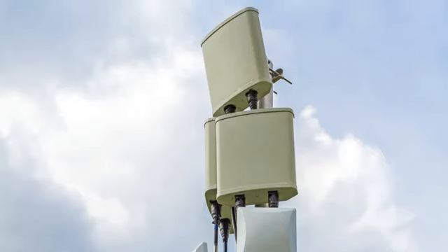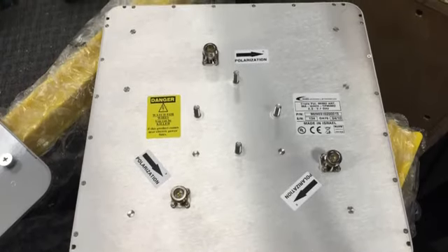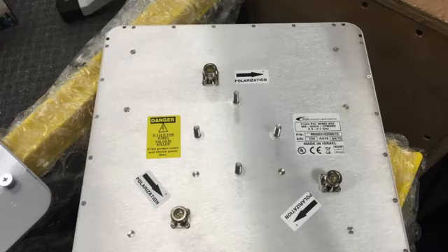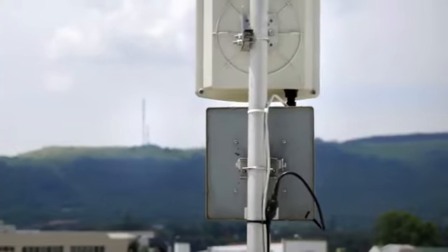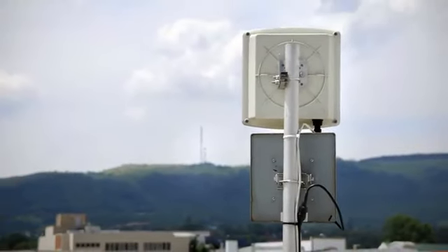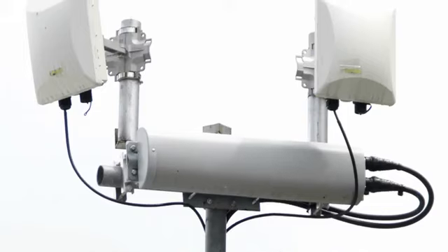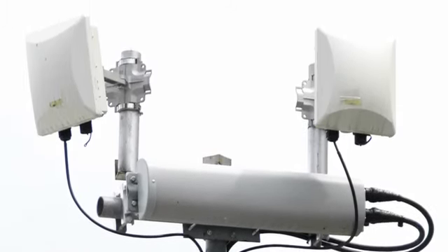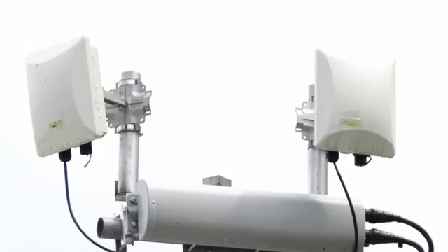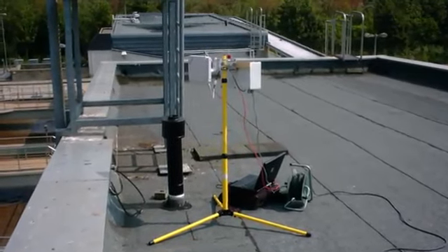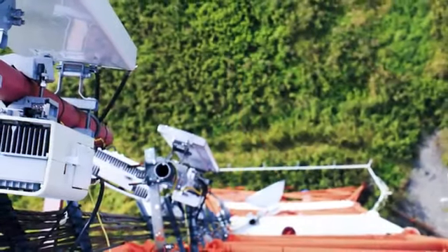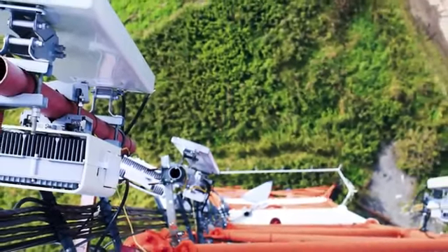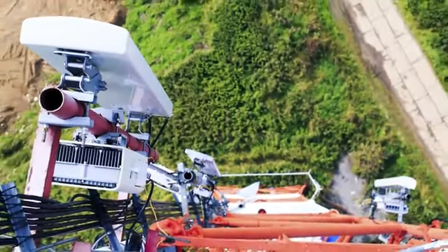Panel antennas, also known as patch antennas, are another common type of directional antenna. They're typically thin and rectangular in shape, consisting of a sheet of metal mounted over a larger sheet of metal called the ground plane. These two sheets together form a resonant piece of microstrip transmission line. The low profile and weather resistance of the panel antennas make them well suited to indoor or outdoor applications. While transmitting in the direction the panel is facing, panel antennas are typically not as focused as Yagi or parabolic types, which have a narrower beam. This means that while it can cover a larger area, it will have less gain and range.